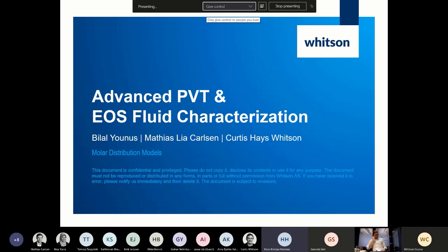It means that you calculate the C6, C7, C8, and C9 molecular weights based on the composition. That is more accurate than Katz-Firoozabadi as a body, and you use those values to calculate the C7 plus. So that is normally a little bit more accurate than the C7 plus you get if you use Katz-Firoozabadi as the pseudo component. Yeah. Very good.